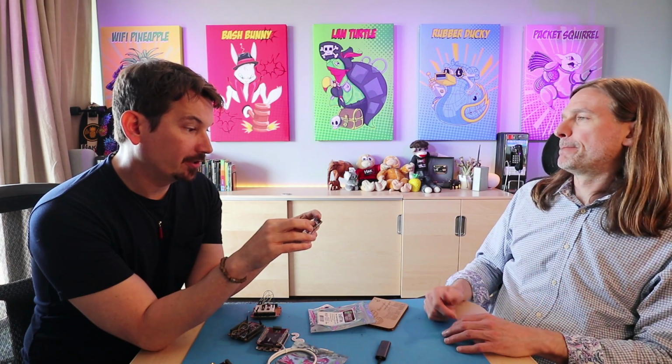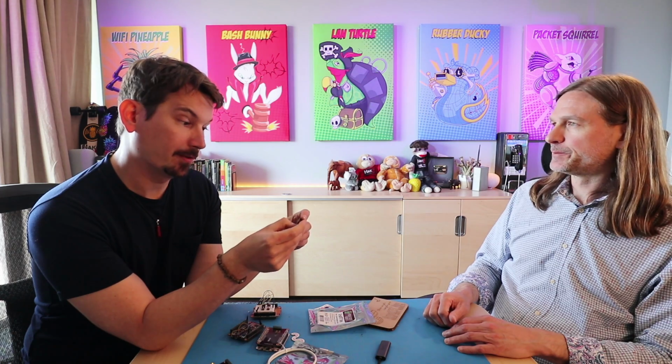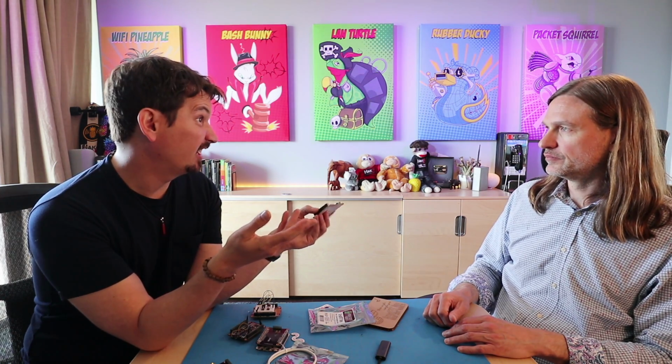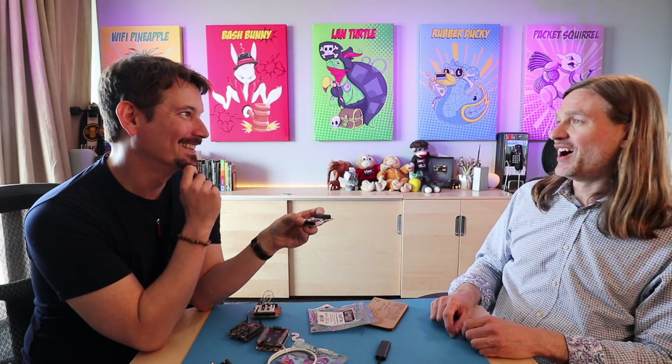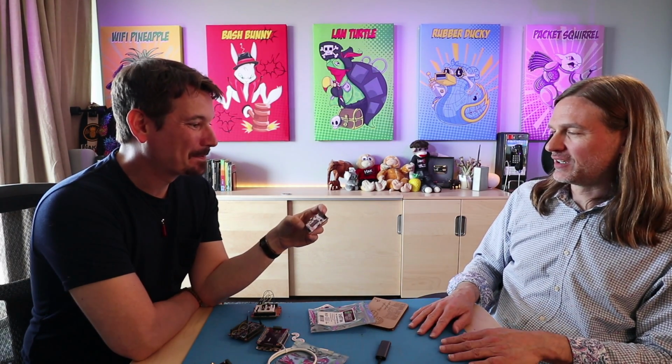Oh, right. And since all these I/O pins are 3.3 volt, as it says right here on the board, I wouldn't need much more than just an LED stuck into it, right? Right. Well, you probably want a current limiting resistor. But okay, I was thinking a 3.3 volt LED, but yeah. Basically, you can just plug an LED in and it works as long as it has some kind of protection. But it gives you the opportunity to experiment with external things. Maybe you want to wire up to another piece of hardware and probe it or manipulate it in some way.